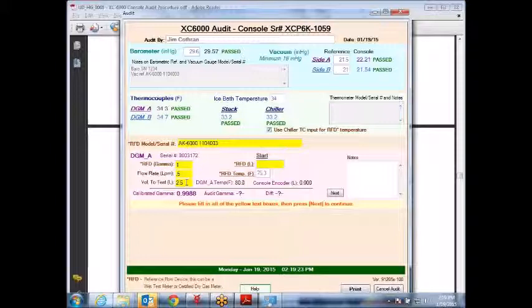Okay. All right. On the front of the reference meter it's a Red Lion totalizer display. It's showing you the volume for the reference device. What I'm doing is hitting the reset button, so it's reading all zeros. That's my starting point. I just put in a 0. Okay. All right. And got everything, Dave. We're good to go.